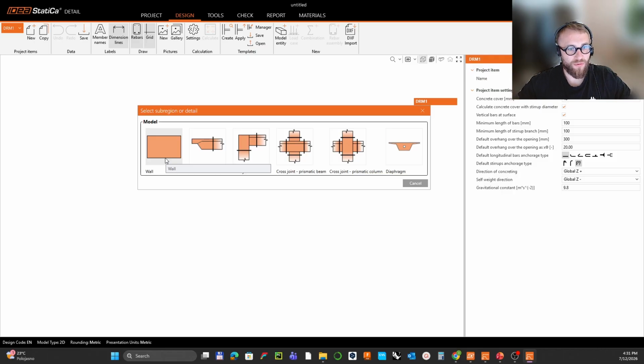It's not developed for this reason, and you're able to specify only some arbitrary shape with a specified width that defines the stiffness of the structure, but the stirrups will not have the same shape as in the beam. So the wall is quite a general approach, while the beam is more specifically oriented for beams. For my purposes, I use the wall, but if I select the beam for this type of structure, I will receive the same results. So both options are correct, but I will select the wall.